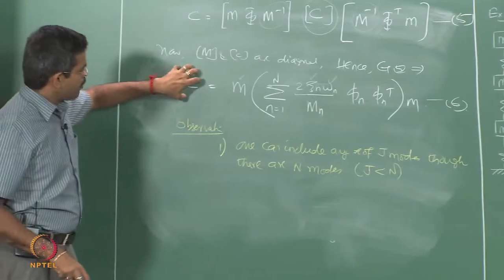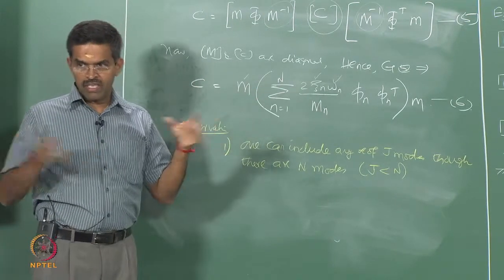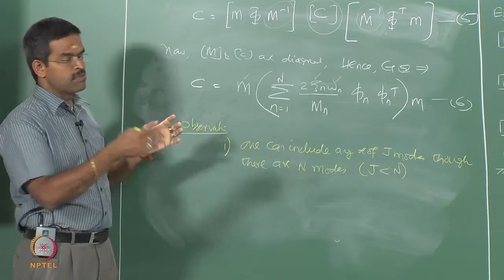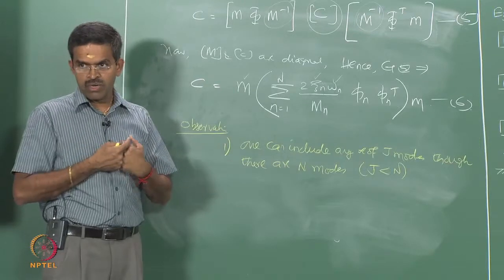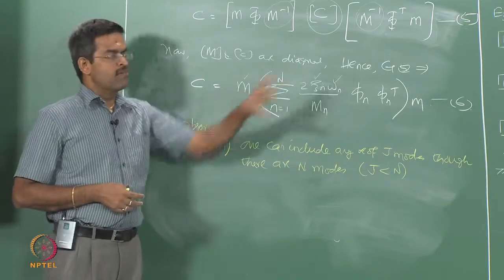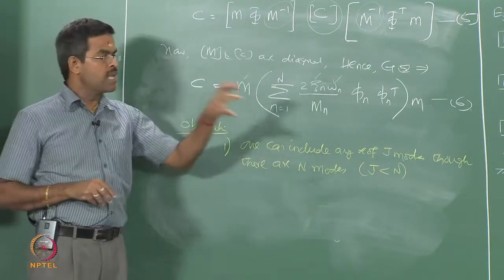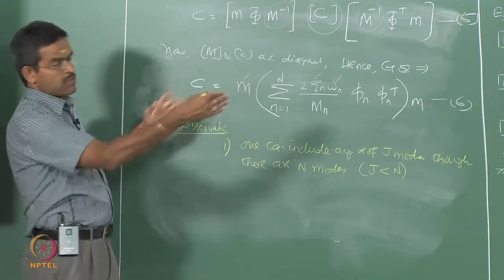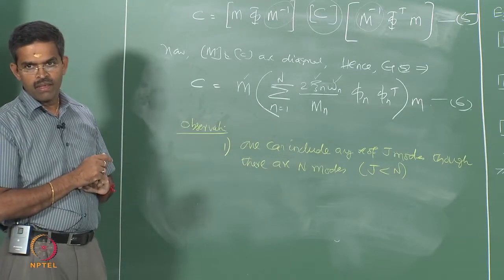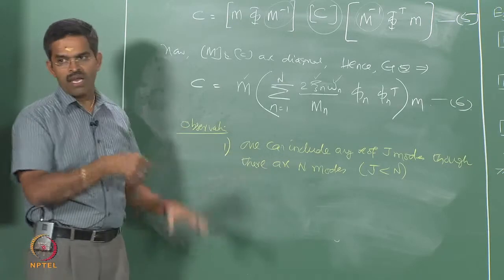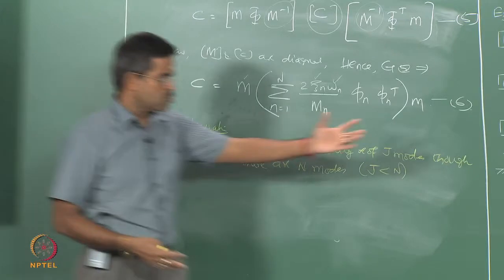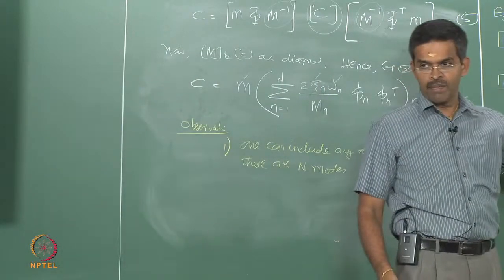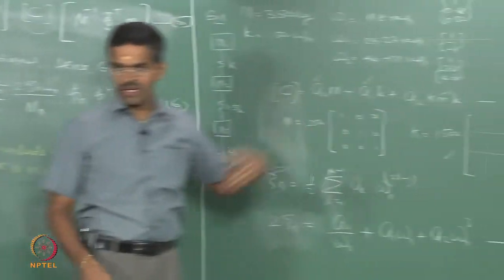It has been found to be proportional to mass and stiffness separately, independently, but practical examples and experiments show that they are neither mass proportional nor stiffness proportional. So, Rayleigh suggested we take a component of mass and a component of K, say a0 M and a1 K, and found a matrix, and that gave me the liberty of truncating higher modes. But Caughey extended that, saying let us go for higher modes also, but it did not show me significantly. For this example, it is going to be similar to Rayleigh damping.